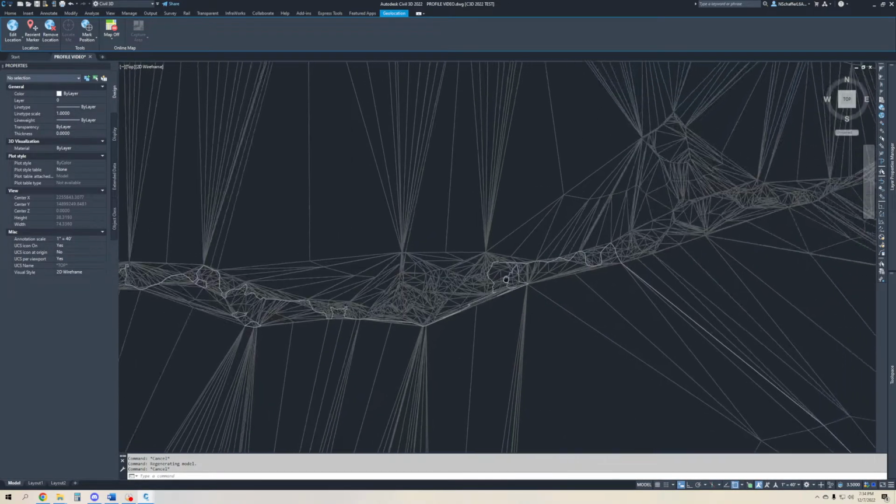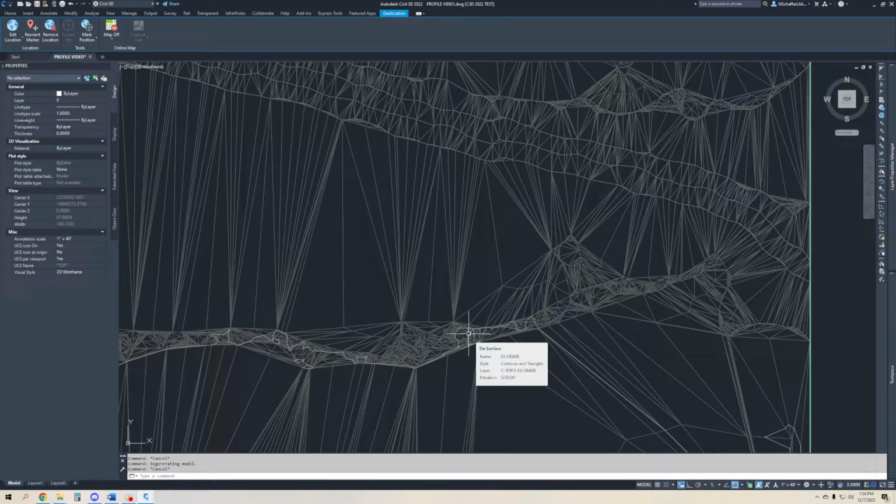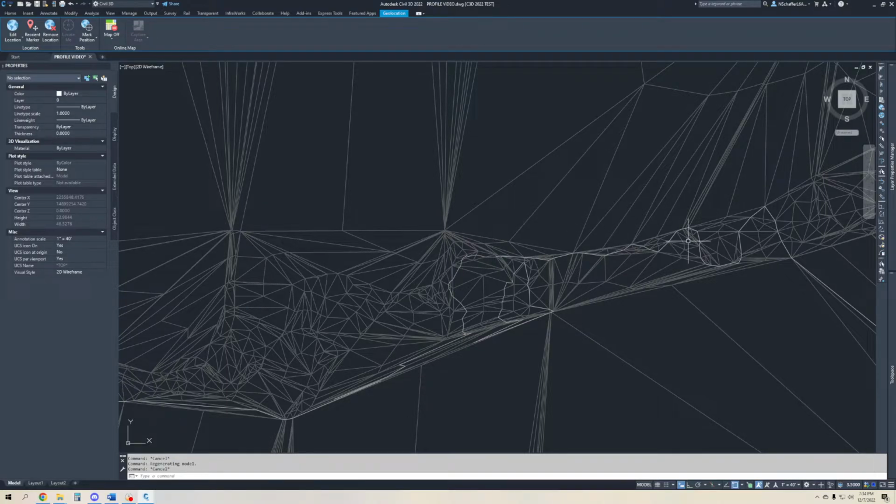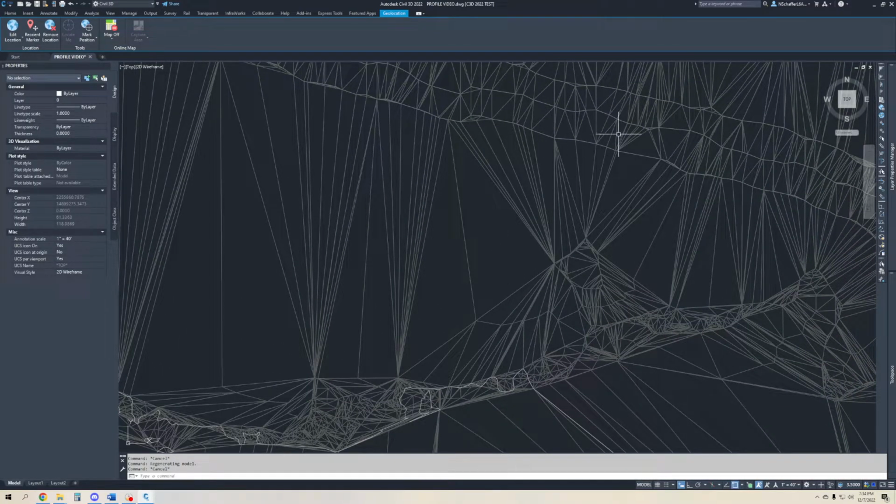And when we hit a major elevation or a minor elevation, so either every 2 feet or every 10 feet in this case, it draws a contour line, which this white line here is a contour line, and we have some 2 foot contours. So that one's 5,228 feet. And this one over here is going to be 5,230 feet. So it is 2 feet in elevation difference from this line to this white line. So that is a tin surface.